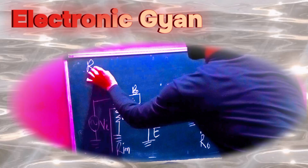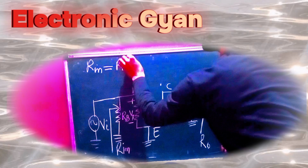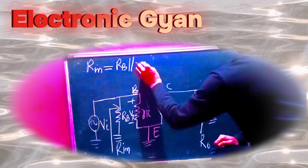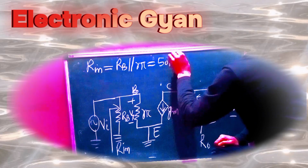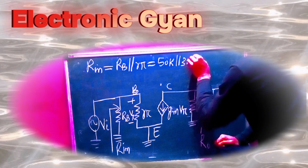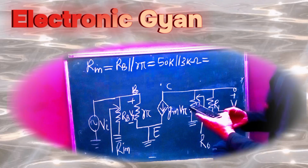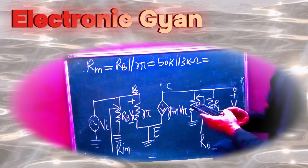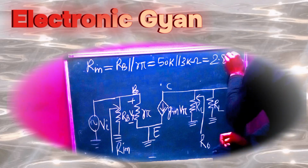So our input resistance is RB parallel R pi, which is equal to, RB is 50 kilo ohm, and R pi is 3 kilo ohm. If we solve this, we will get 50 into 3 divided by 50 plus 3. So this is 2.83, so it will come 2.83 kilo ohm.